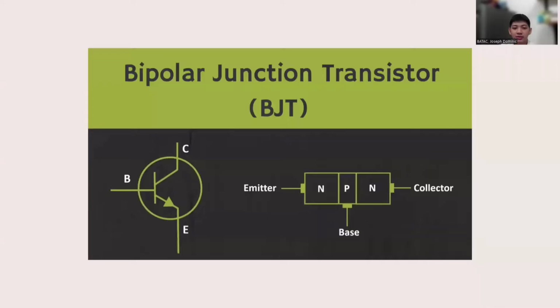Introduction. Bipolar junction transistor or BJT is a three-terminal semiconductor device with three layers that have different degrees of doping in each of the three P and N layers. A bipolar junction transistor has three distinct sections: base, collector, and emitter. A transistor acts as an amplifier by combining weak and strong impulses, increasing the circuit's output power. The DC bias voltage ensures forward bias of the emitter-base junction.